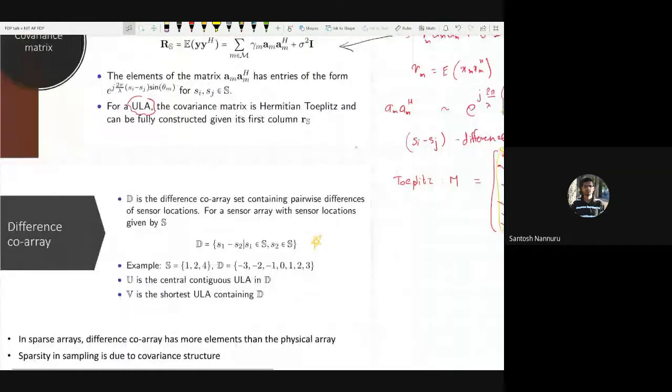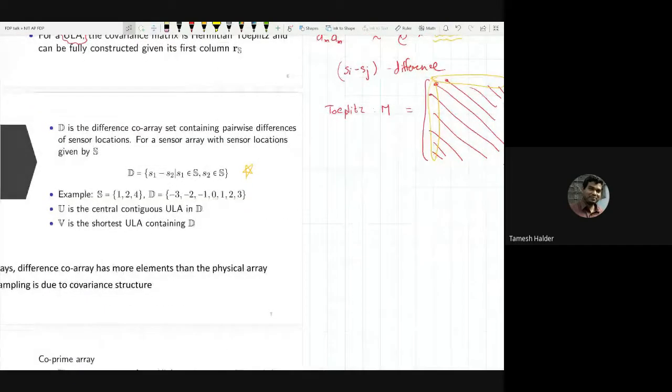Is the sampling linear or non-linear? You mean the array coordinates? Yes, sir. They are integers. The question is whether the spacings between them follow some linear or non-linear function, unequal spacing. For uniform arrays, the spacing is fixed, constant. For sparse arrays, as we'll see, the spacing can change.